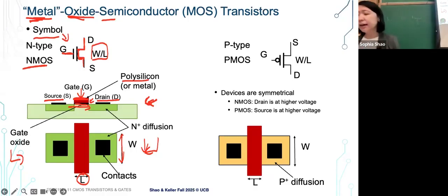So far, so good. Okay, so this is basically the N-type transistor. And similarly, we also have the P-type transistor. At a simple level, instead of just applying the gate here, we have a circle here, meaning it's the negation of the NMOS. The devices are really symmetrical, but for NMOS, electrons are flowing from source to drain. For PMOS, it's more like holes are flowing from source to drain, just with a relatively different voltage potential between source and drain, and that leads to different behavior.